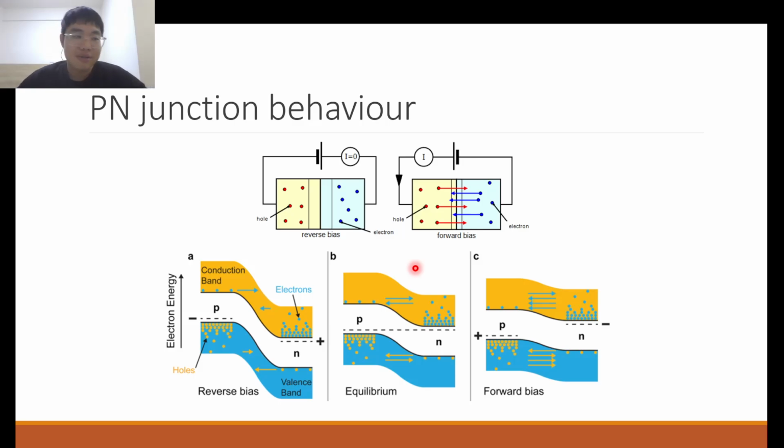And so when you have your layer which is devoid of charge carriers, only having fixed charges, when it is very thick, it impedes current flow through it; very little current can flow through it. And so therefore we see that the p-n junction effectively does not conduct electricity in the reverse bias state.